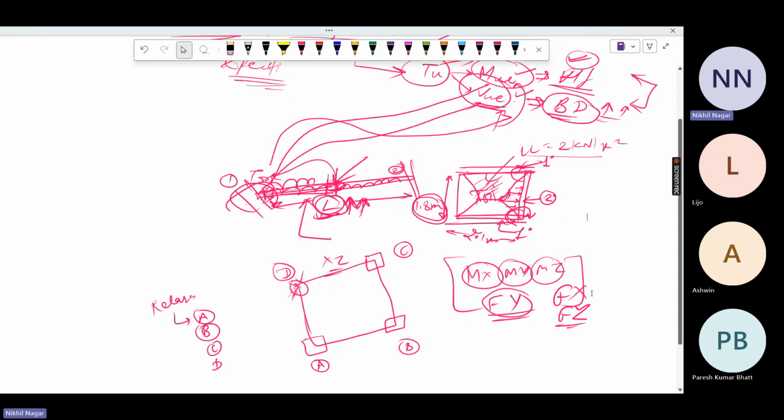No, all the releases. Fx and Fz are for special cases. If there is not any restriction, it means there may be a beam passing from here and also at the level below. It means it can't go left in this direction X or in this direction Z. So in that case, you have to give Fx and Mz. But if there is not any restriction in this direction, then you have to take all as a release. It is just overhanging, as a category of beam.